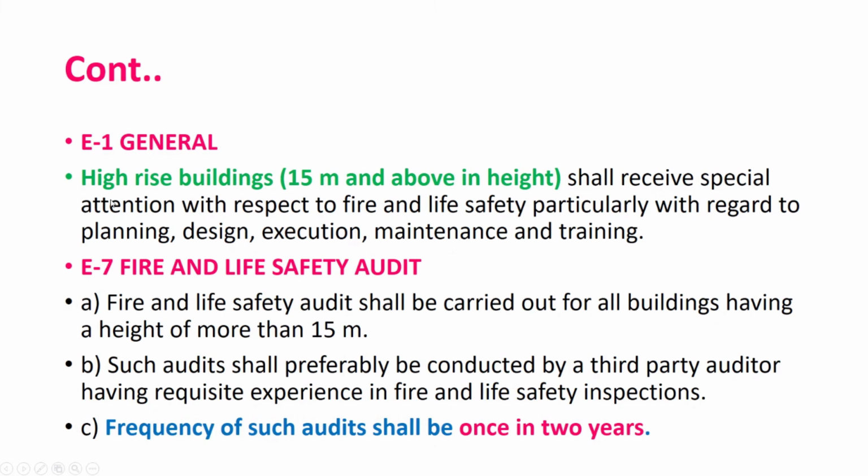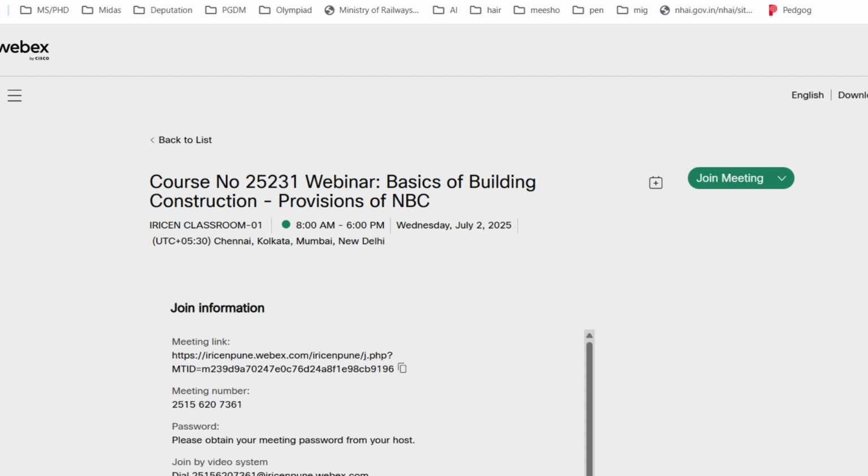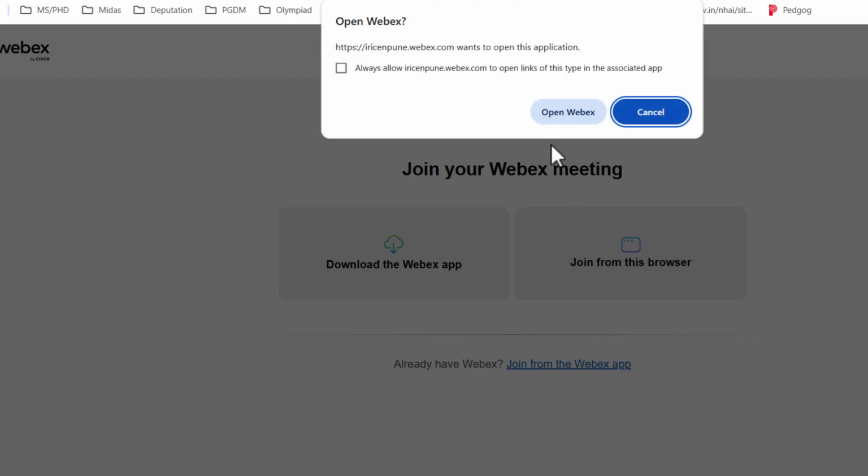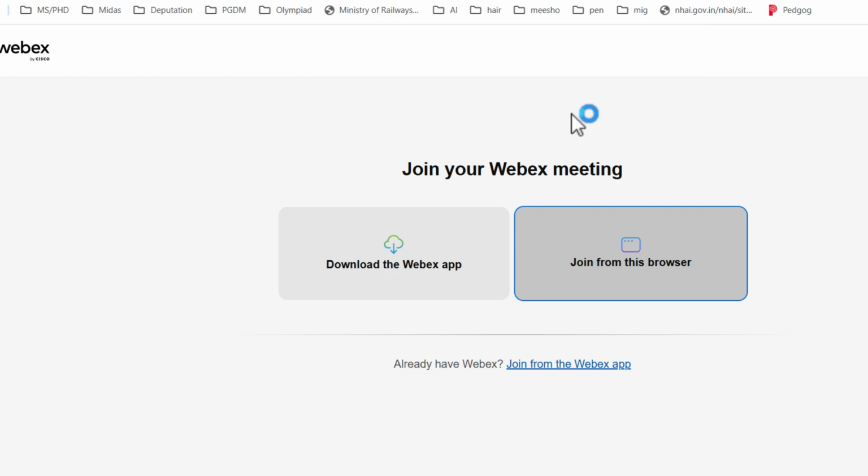Very important, because big structures are coming up nowadays, maybe you are making certain quarters also. So here the hard surface should be able to take 45 ton load. So you will be required to do the design of that particular road also. Maybe in case it is required, you have to do RCC of adequate thickness and adequate grade of concrete. So I suppose this is known to all. Very important requirement.